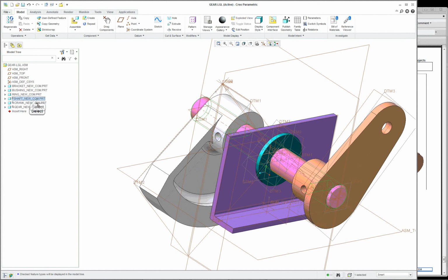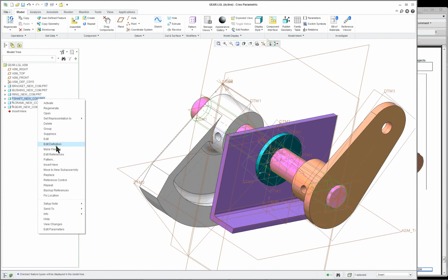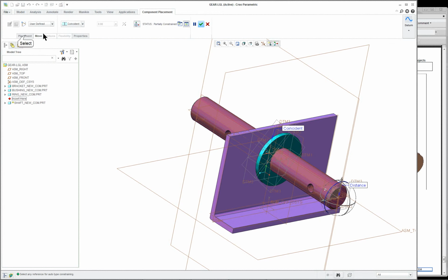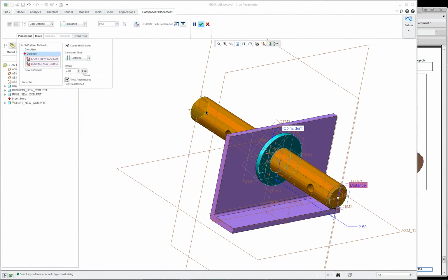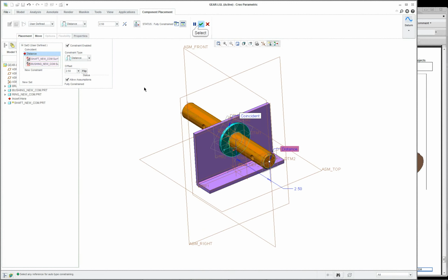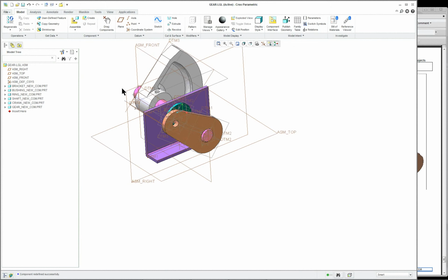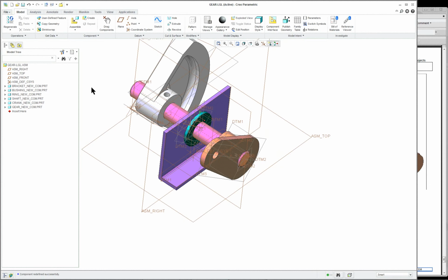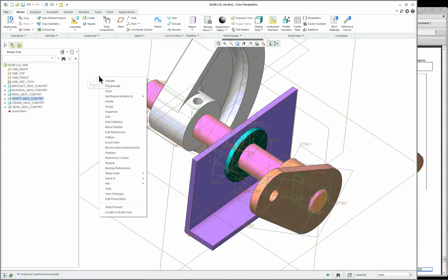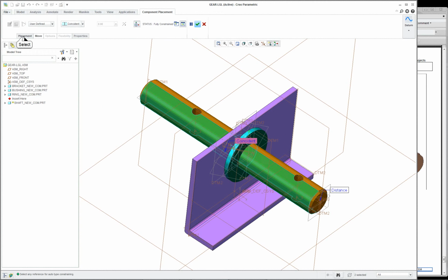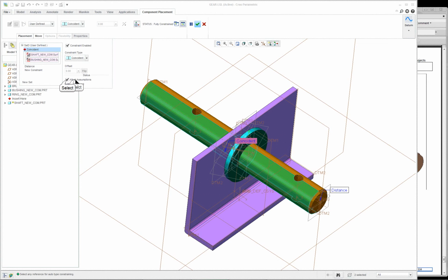You'll notice it says here the shaft is incomplete, and we have a distance here. If you allow assumptions and we come out of that, then that little box that was here would disappear, because it was showing that it wasn't fully constrained at that point. By changing the assumptions, if you uncheck this, it's going to want another constraint, and we can add a new constraint.